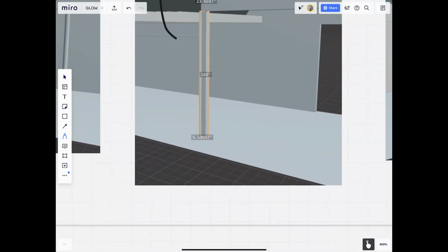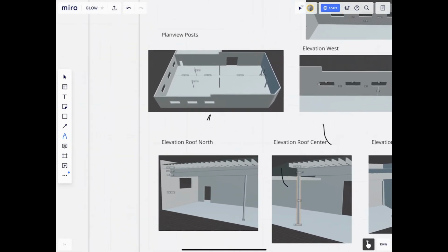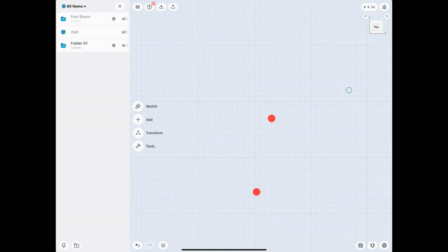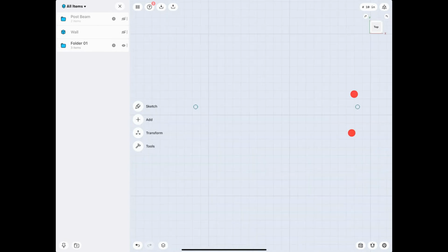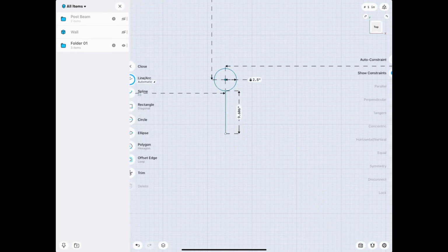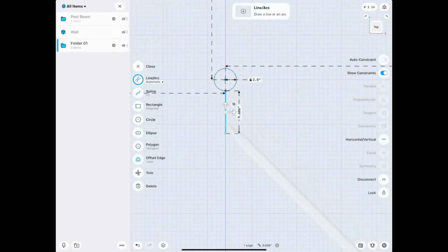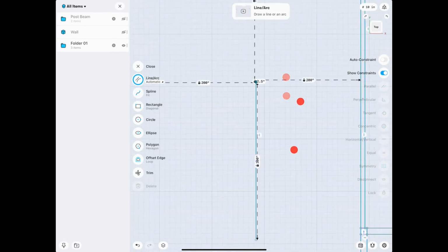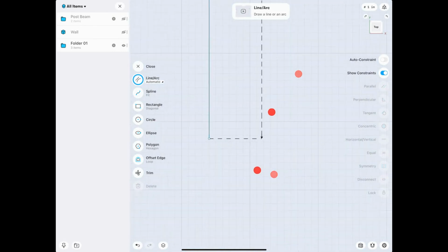The I-beam has a dimension of 9.6 by around 8, and the distance is 300. So check this out. Now we'll go to here. Draw myself a line. This one I lock so it can't move. Make it vertical so it can't rotate. And this should be 300. So I know exactly where I have to put my next sketch to.